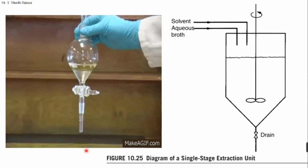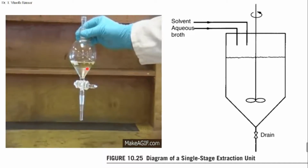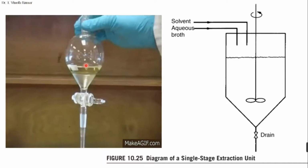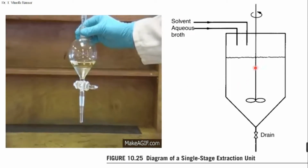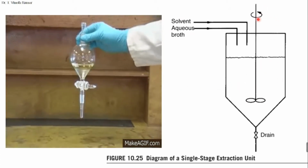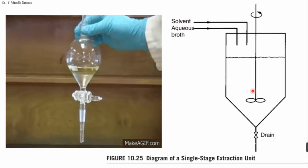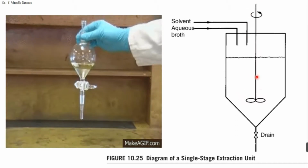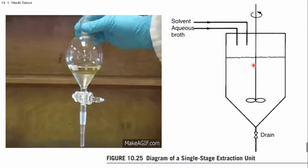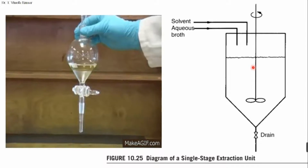Okay, this is the separating funnel. You can see here this is one phase and another phase. This is the aqueous phase and this is the organic phase, and this is a model of a separating funnel. Usually you can mix it manually, or otherwise on a large scale in the industry, they will use a mixer with a rotor attached, rotating at approximately 2000 to 3000 rpm.